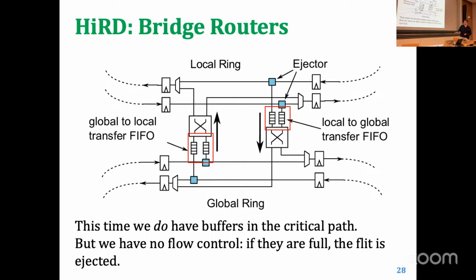But the big difference with regards to a conventional hierarchical ring is that in a normal hierarchical ring, when a buffer is full, the flow of information in all the ring is blocked. There is a special flow control unit which requires some more computation and takes care of that. But in this case, if the new flit cannot enter the buffer, it is just deflected, and so it will make another round of the loop of the ring.